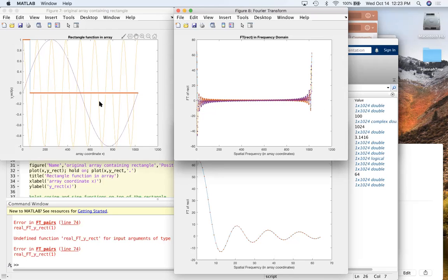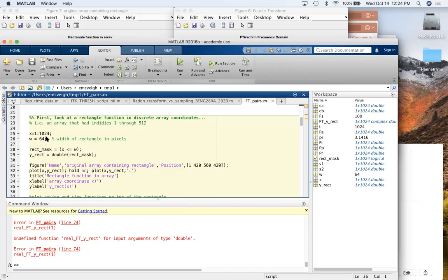So with this discrete Fourier transform, because you always have a finite sampling interval, you will always have this interval where the replicant occurs, and you just have to set your sampling rate in your function such that the frequencies you're interested in don't overlap with the next replicant of the function. Let's go the other way. We could say, well, let's radically undersample it.